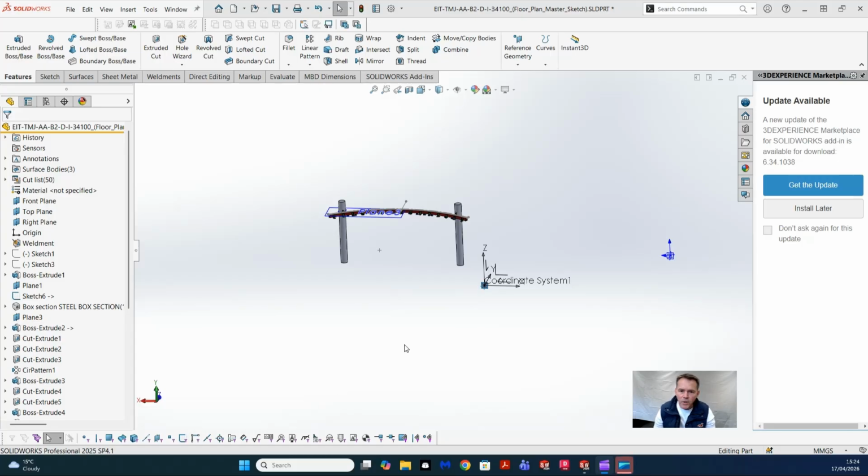We're going to look at adding an additional origin with a new coordinate system for SolidWorks in the part environment, but you can also do this in the assembly environment by the same method. This can be quite useful if you're collaborating with other members of your team or other businesses, other colleagues, and they're all maybe working in different 3D software, or you want to establish different origins to the ones that you originally modeled in.